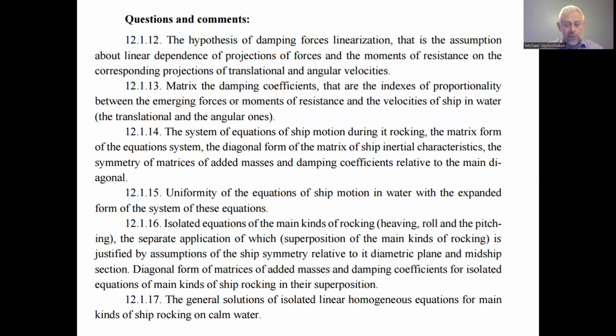12.1.14. The system of equations of the ship motion during its rocking, the matrix form equation system, the diagonal form of the matrix of ship internal characteristics, the symmetry of matrices of added masses and damping coefficients relative to the main diagonal. This symmetry looks very much like the symmetry of the matrices that we probably remember,